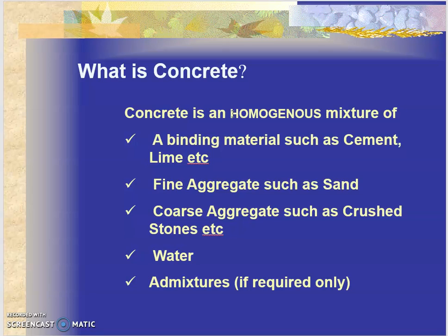So let's say when you start adding water, in a matter of initial setting time, final setting time, we have already studied when we did cement, right? We studied cement as a material. So after 30 minutes, if it starts setting, then by the time it hardens, let's say you want it to harden very quickly, or you want it to harden very slowly, because you are transporting your made concrete from, let's say, your RMC plant, ready mixed concrete plant, which is at Ponda and your site is at Margao. You want to delay the setting, then you get something called retarders.